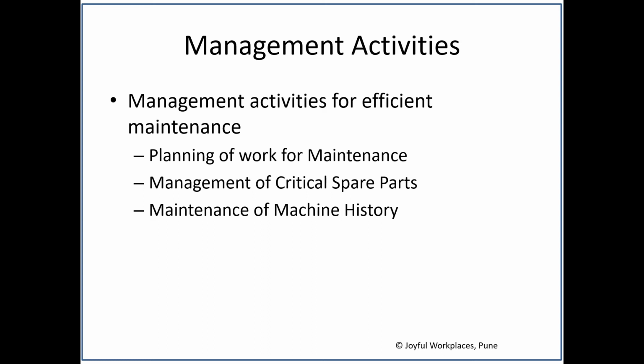Management also needs to identify the critical spare parts. What are critical spare parts going to do? Management of these parts will ensure that your breakdown time or repair time is as small as possible. Just imagine a situation when the machine goes into breakdown and you don't have the critical spare part with you. So what will you do? Either you will go outside and raise a purchase order, and then the lead time will start, and after some days the critical part will arrive. Till then it will be under breakdown.